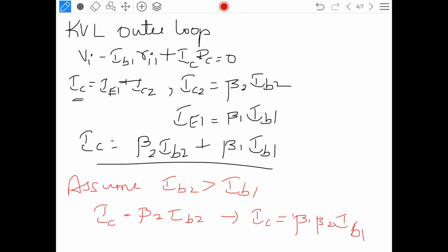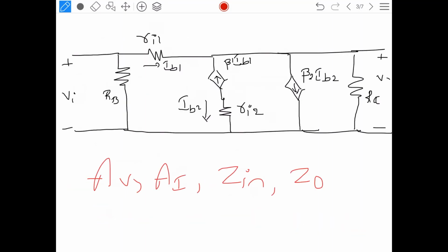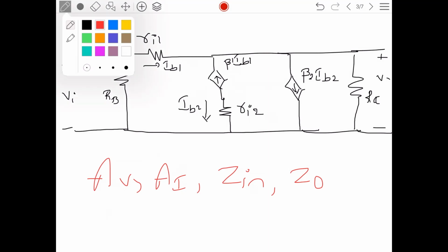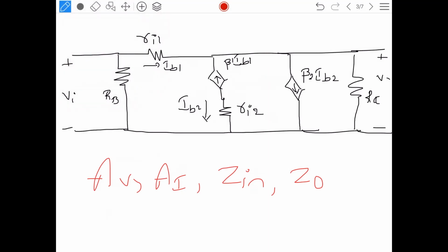Putting all this substitution, the circuit input impedance and output impedance have to be calculated. So, writing on the small signal model, I am representing the impedances here. If I see from here, I will get Zin. At the same time, if I see from here, I will get ZB, which is the same way we had already written for the Darlington.